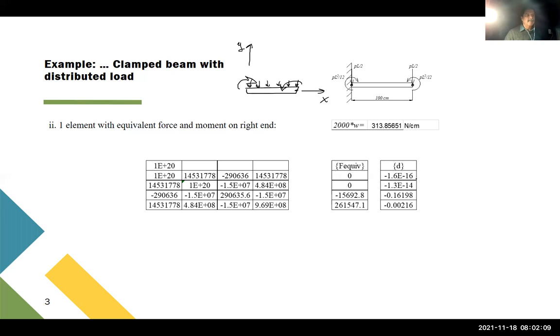Again, displacements are very small, extremely small, basically zero. And these are the displacement on the right end and the rotation. Signs, we assume that they are correct. We multiply this, not times this, because we have altered these two values. We multiply this times the original stiffness matrix, and we got these are the external forces. Okay, these two values correspond to this, and these two here.